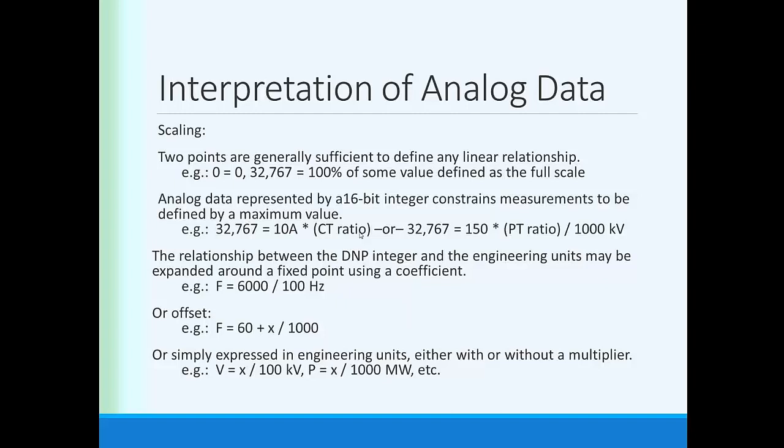And then I can give you an integer in the meter that you divide by 1,000, and that will give me resolution, plus or minus 1/1000th of a hertz. So when I take the data, I have to take the integer from the IED and divide it by 1,000. That could be a positive or a negative number. And then I add that to 60, and that gives me my frequency with a resolution down to 1/1000th of a hertz.